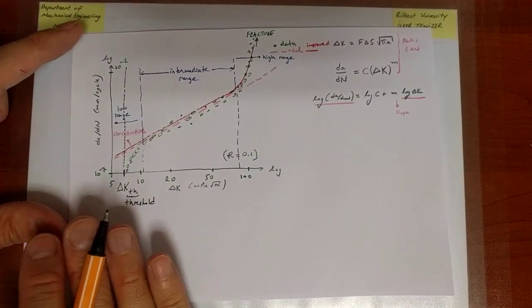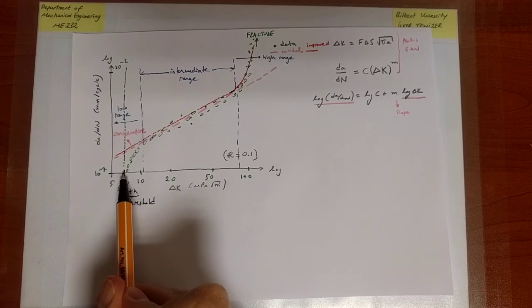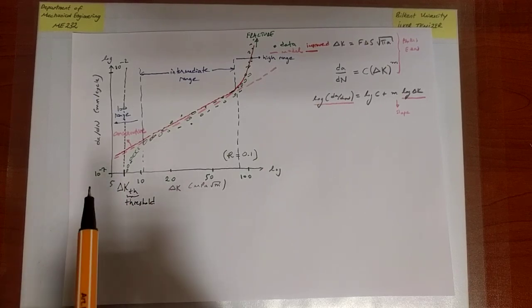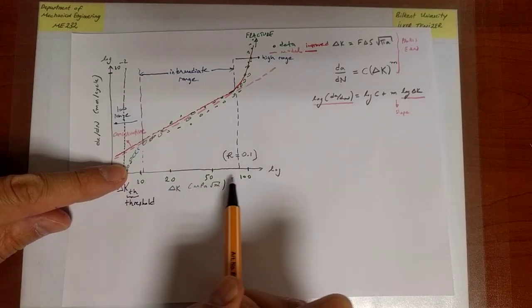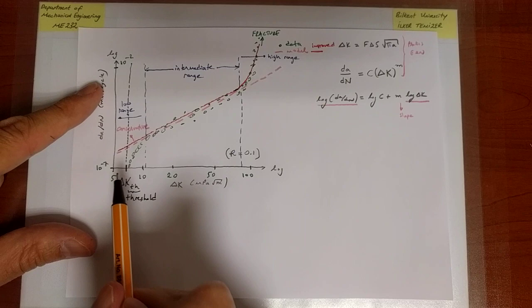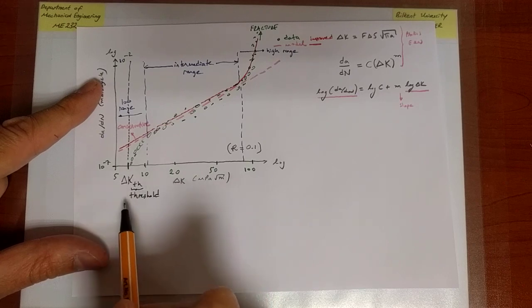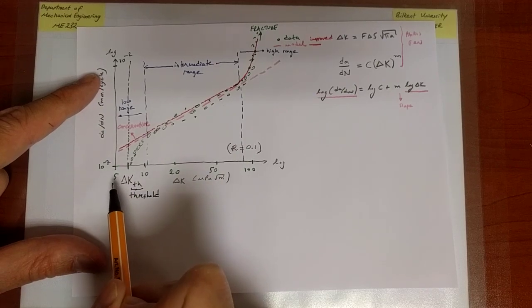So if I have a certain crack size and if I don't put a lot of load on it, then I observe from experiments that sometimes, maybe not always, the crack will just not grow. We've said that the cracks will grow if you cycle the load. For most amplitudes of load cycling, that is indeed the case, but it turns out for some materials and for certain limits to the range of the load, or more properly, limits to the stress intensity range, there is a certain threshold value below which the crack would stop propagating.